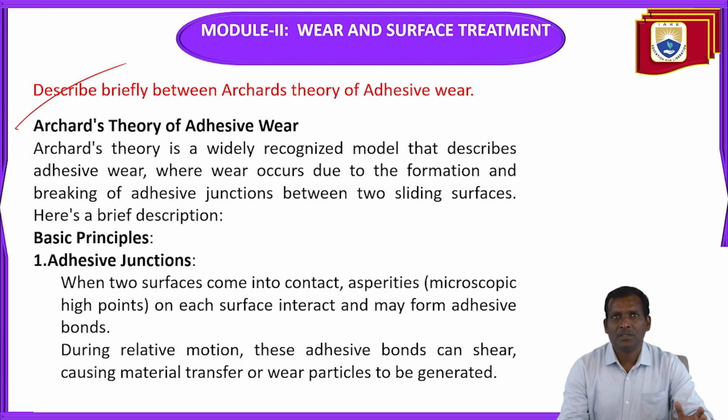So the basic principle of Archard's theory: the adhesive junctions. When two surfaces come into contact, microscopic asperities on each surface interact and may form adhesive bonds. During relative motion, these adhesive bonds can shear, causing material transfer or wear particles to be generated.